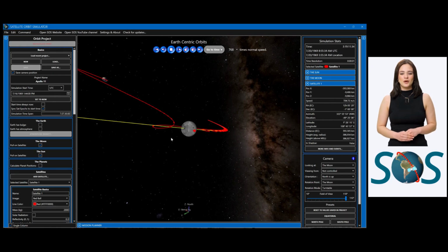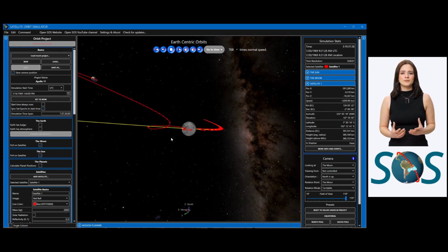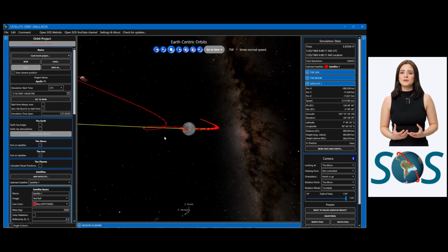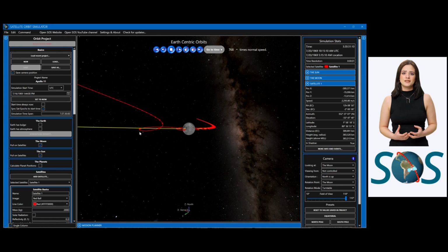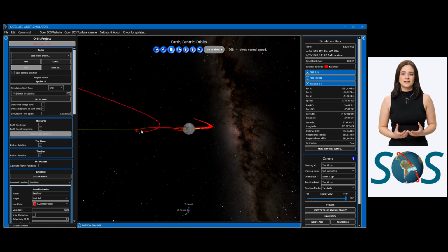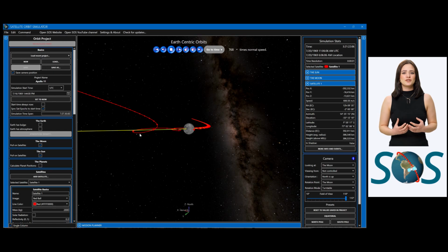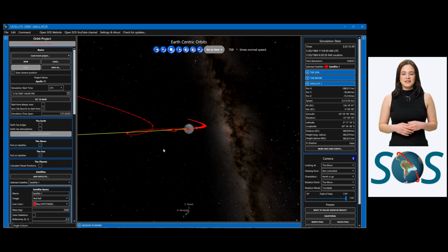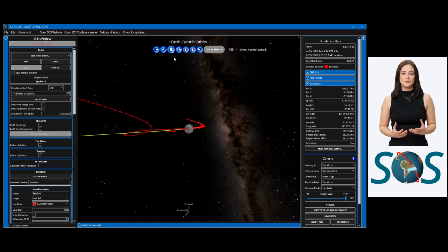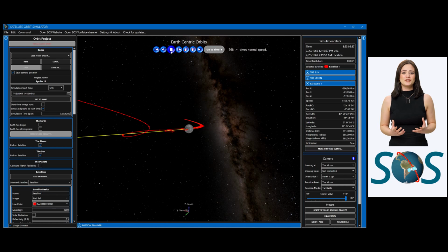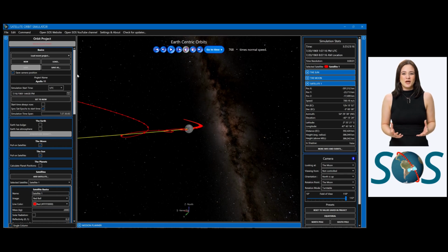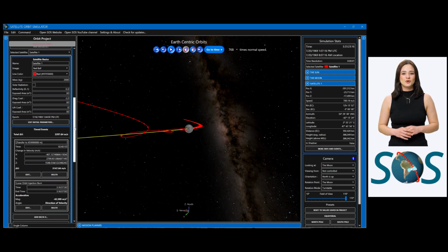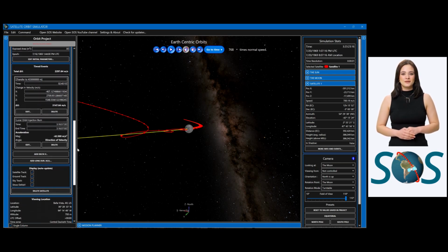At 6:41 and 30 seconds AM UTC, the lunar orbit injection burn occurred in the opposite direction of velocity and behind the Moon. We use 42.5 meters per second squared of deceleration for 20 seconds. This is slightly more than 4 times the acceleration due to gravity and can be tolerated by the human body for short periods. The spacecraft then slowed to enter a low-altitude lunar orbit.